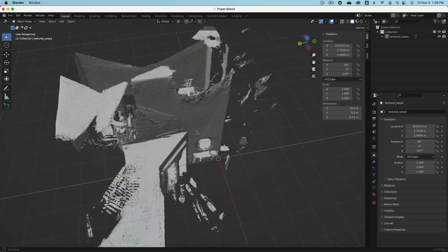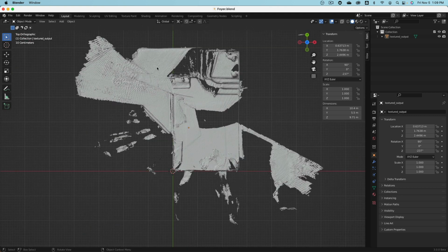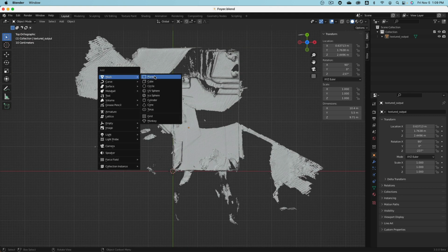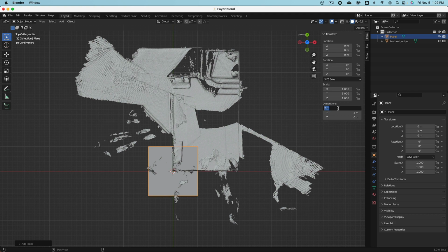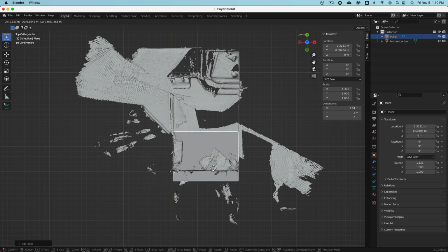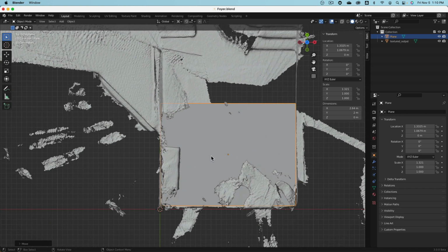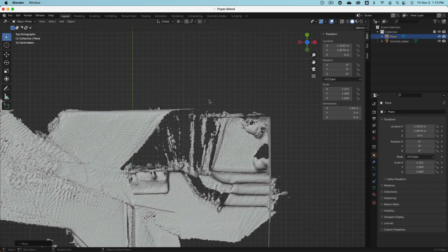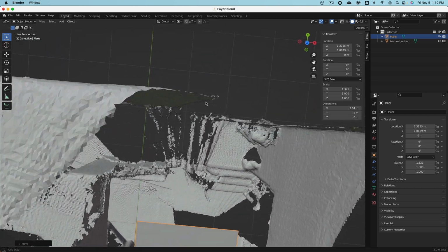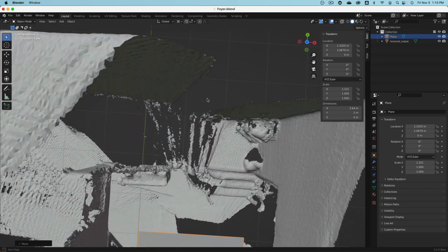And there we are. And if I bring in a measurement plane just to verify, this should be 8 feet, 8 inches. That is the internal measurement. There you see the scan is actually pretty precise. Also here, when I go back to this back face, there you can see how this is not aligned.